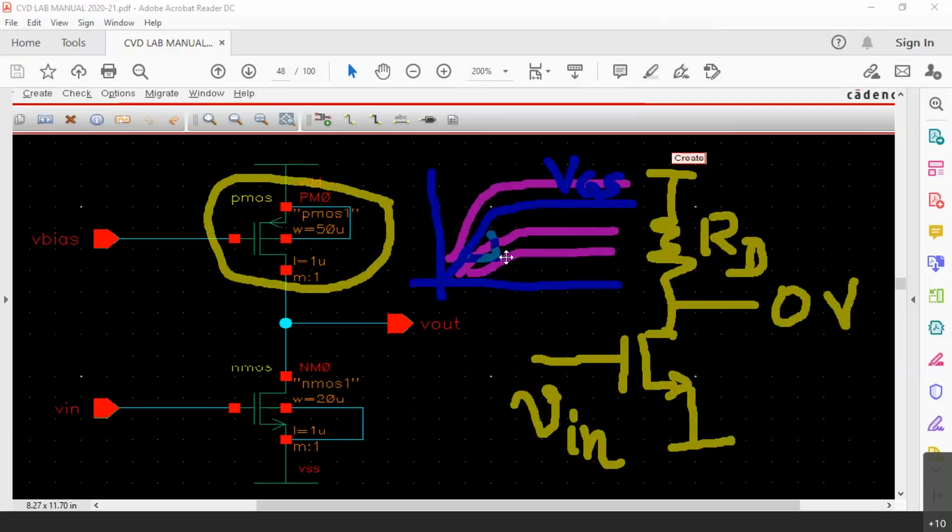But in this region, whether it is the ohmic region or the linear region, it is called ohmic because it is working like ohms. It is a resistor only. Now we fix a particular VGS such that we want a particular value of resistance. For obtaining a particular value of resistance, we can fix a value of VGS and we can fix this Y by X. That is, sorry, X by Y. X axis is voltage, Y axis is current. So X by Y is nothing but the resistance.